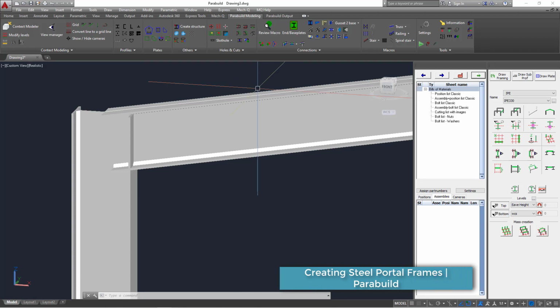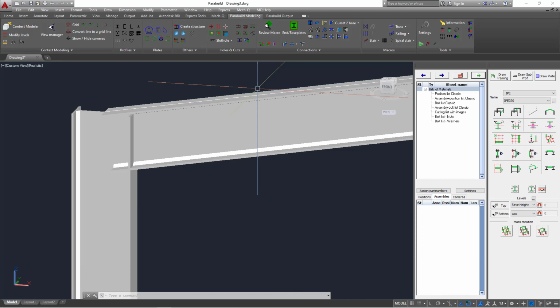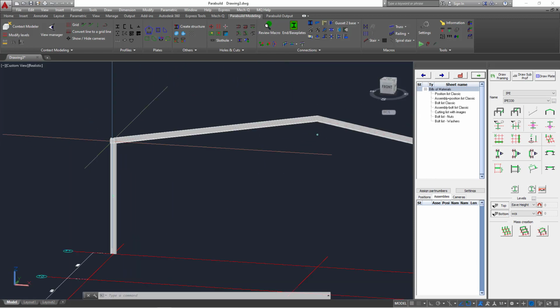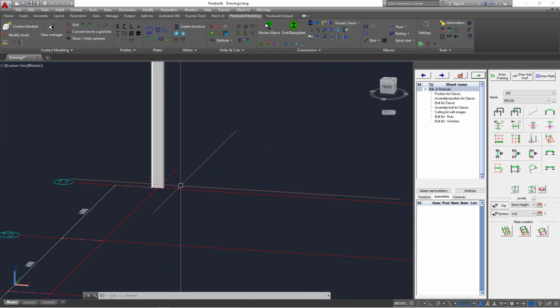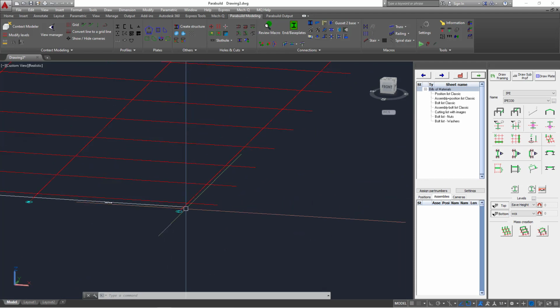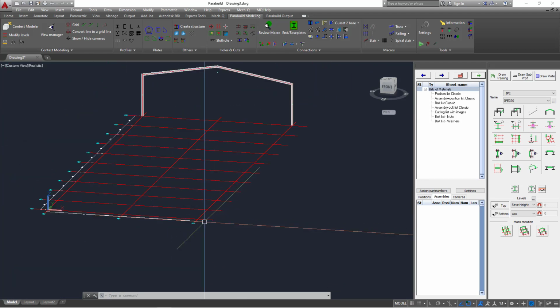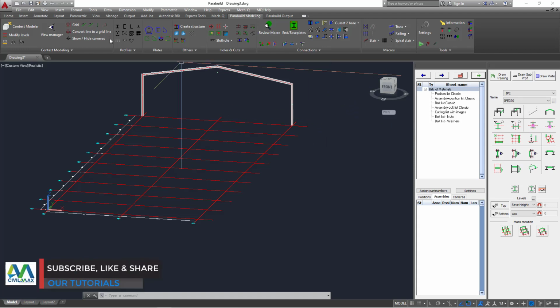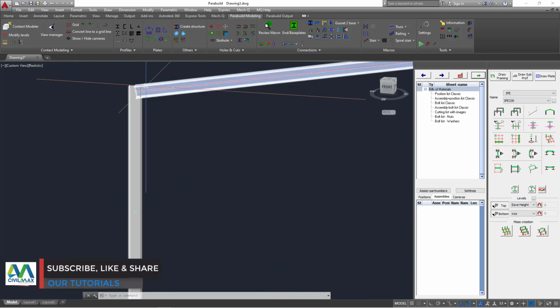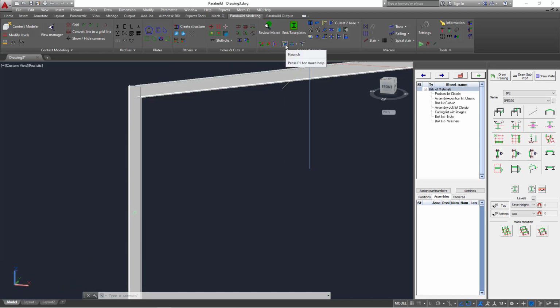So I'm going straight to start creating connections. The connections are haunch here, and the apex and the base plate right here. Then we populate everything to the full length of this particular structure, or to the full length of the grid line. So in here, let me go ahead and pick on the haunch under connections. I'll come to haunch here, just mouse over, and you'll be able to see the description right there. I'll click on the haunch right there.